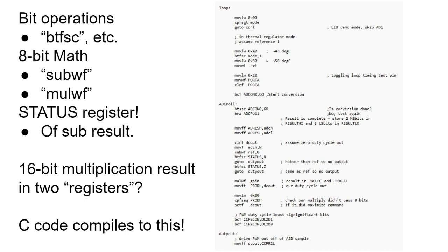It's a low level machine code, a relatively small set, some dozens of them supported by an 8-bit microcontroller such as this. All of your C code compiles into these types of instructions. So one line in C could be 10 lines here, or 4 or 6. We can later look at compiler output and see how a compiler for a specific family of devices, a specific architecture you call it, this here is a PIC-18 Microchip PIC, how that compiler would produce machine code from your recognizable C code. So here's a bit set F.